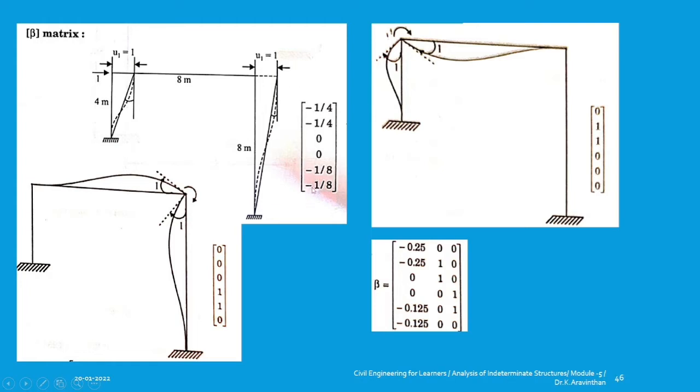both the ends. So the highlighted point here is, when you are considering the sway force, you have to take the stiffness component only for the column. So no need to consider the beam, stiffness only for the column. The deflected distance divided by the original length. So this will be the sway.